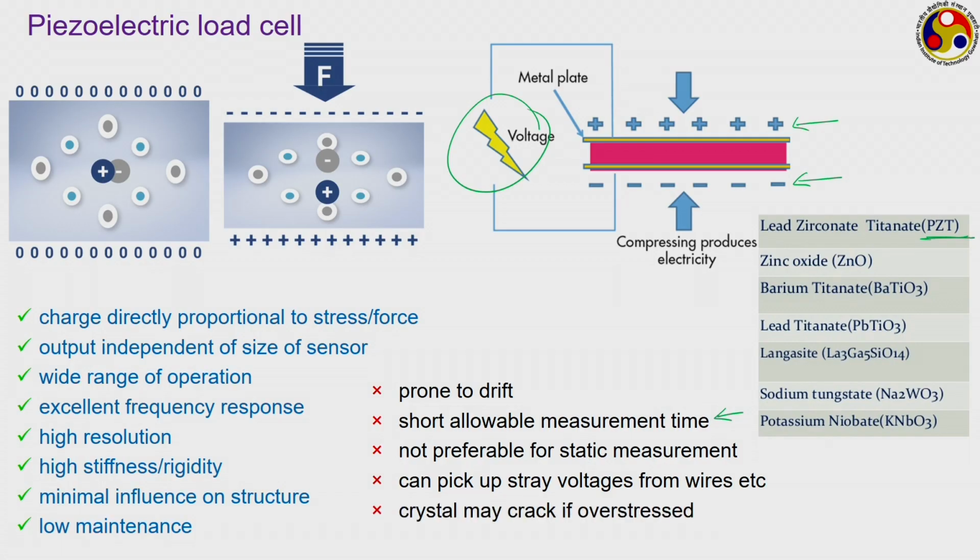And the crystals may be quite delicate, so if they are subjected to over pressure, they may crack or deform, and prolonged use at high temperature must be avoided, because they may show some kind of mechanical deformation when they are subjected to high temperatures for long duration of time. Despite these problems, piezoelectric load cells are here to stay, and they are probably the most suitable device among all the ones that we have discussed so far for dynamic force measurement.